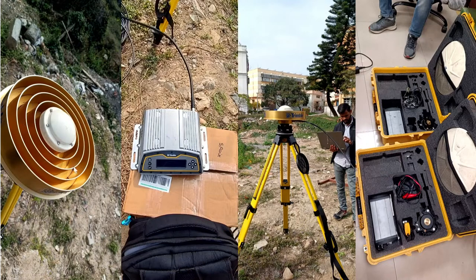The purpose of the choke ring antenna is to reduce multipath, because we know that when the GPS, our GNSS satellite, transmits the electromagnetic wave, it comes in right-handed circular polarization. And here the antenna is intended to receive only that polarization. If there is left-handed circular polarization, it will not receive it. So the purpose of this choke ring antenna is that if a signal is coming from a low horizon or has huge multipath, it can be reflected back and this polarization can be converted with the help of this technology. And this is the campaign antenna as well as receiver, and this is your net and receiver.